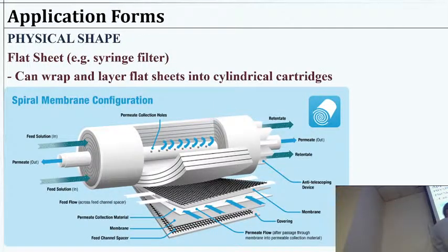But if we do have something paper-like, I don't know whose papers these are, but we'll use it. You could take a flat sheet membrane that's, I don't know, not quite a square foot, but we'll call it a square foot. And you could take another and maybe some more, and then as long as you do the plumbing correctly, so that water can only flow either across for the retentate or through for the permeate, then you could potentially wrap these and now we have 3 or 4 square feet of surface area in a little spiral wound membrane module. And that's exactly what is done pretty commonly.